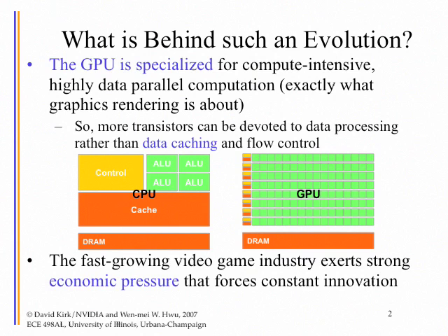So right from the beginning, you design for DRAM latency. And the way to tolerate DRAM latency is not to execute instructions out of order, but rather to have a huge number of threads that can execute on these function units. If one of the threads is trying to access DRAM, you look at these other threads and see if they're ready for using the function units. If you look at the matrix multiplication example, what happens is we will have 256 of those threads.